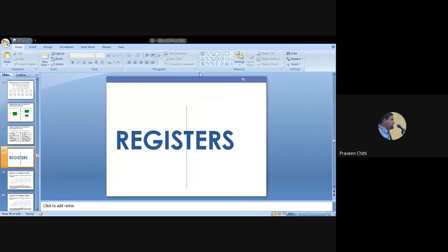Sure, we will start. So in the last class, we ended with the discussion on register. In brief, I have explained register, types of register, shift registers and all. Quickly, we'll see now how exactly we can construct registers. And I told you the best flip-flop that can be used to implement the register is the D flip-flop.